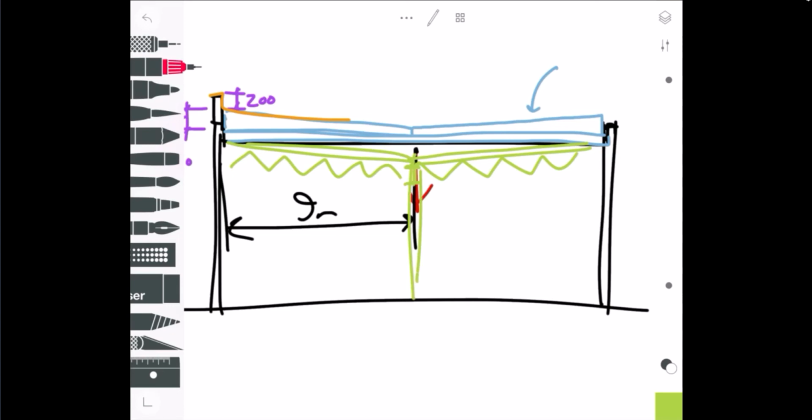The column that the beam would attach to is not as tall anymore, and steel is often paid for by weight. So I don't think it would amount to much, but obviously there could be a savings in there. I think the big takeaway is that you've got to build that structure on the roof anyways. So if you can slope the structure, why wouldn't you?